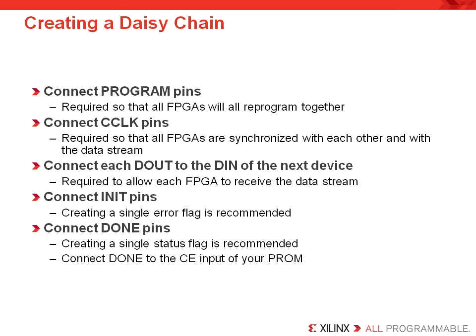As an FYI, check your clock termination and the specifications for the clock signal with the user guide. Again, many customers create problems for themselves when they do not meet their configuration clock requirements. This is probably one of the most frequent technical issues customers experience. They simply do not have a sufficient configuration clock, and the DONE pin never goes high, and they're not sure why.